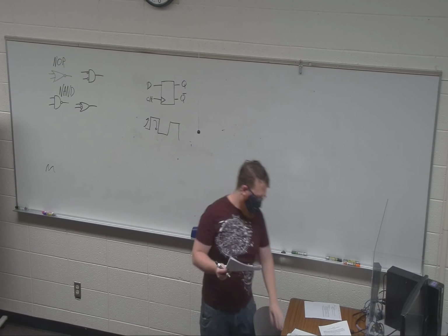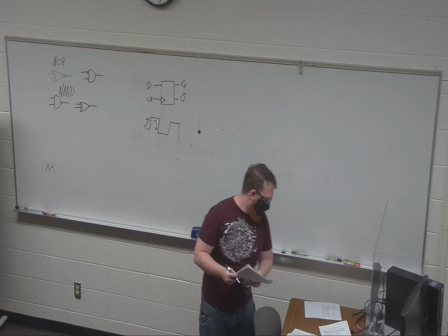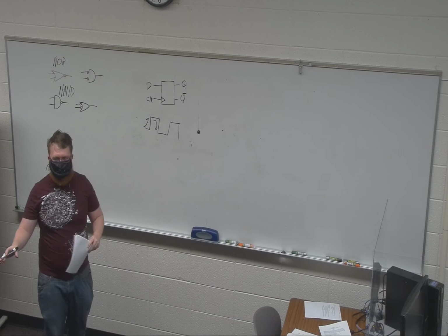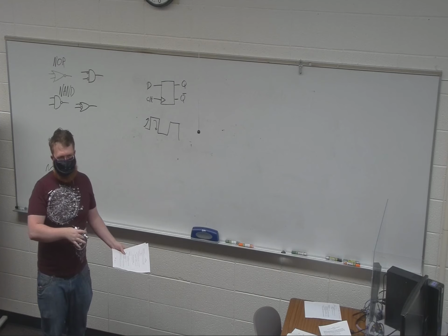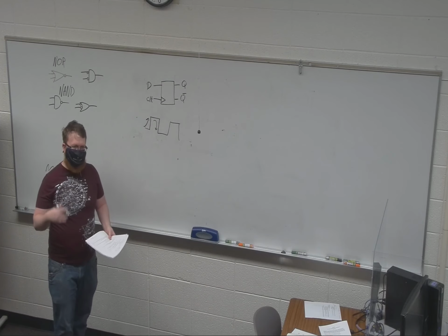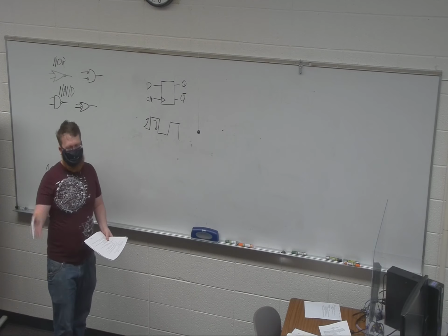An SR latch. So these flip-flops are usually built out of latches, which are then gated. So you gate a latch, which gated really just means clocked, or it has an enable, and the enable functions as a clock.